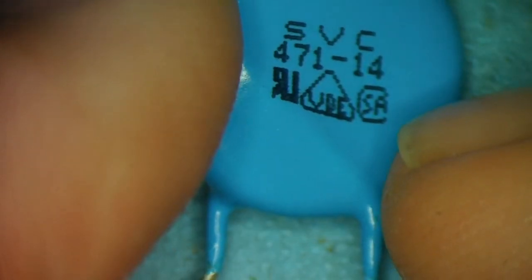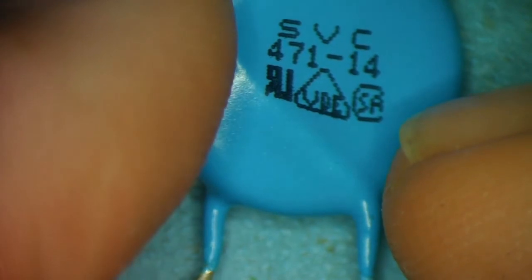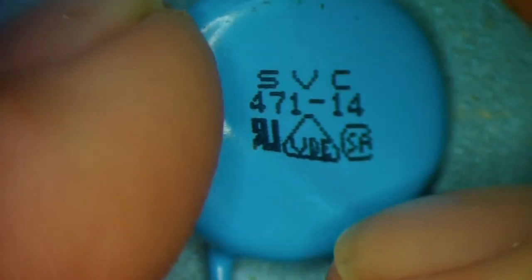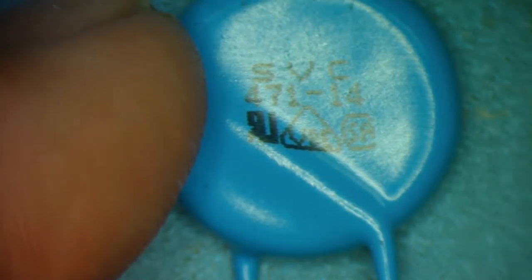This would be used, I'll give you an example, where you've got a circuit with a switch. You've seen power supplies, the older ones, had a switch on the back, and you select 240 volts or 120 volts, yeah? And if you select 120 volts and plug it into 240 volts, you're going to damage something, you're going to blow something up. If you're lucky, it's just a fuse, but you probably won't be that lucky.